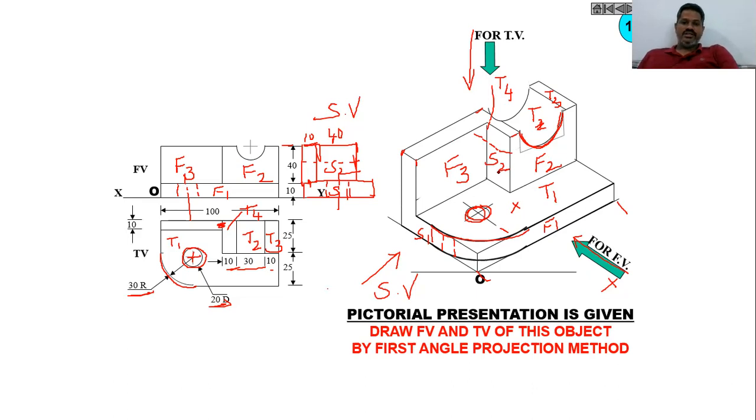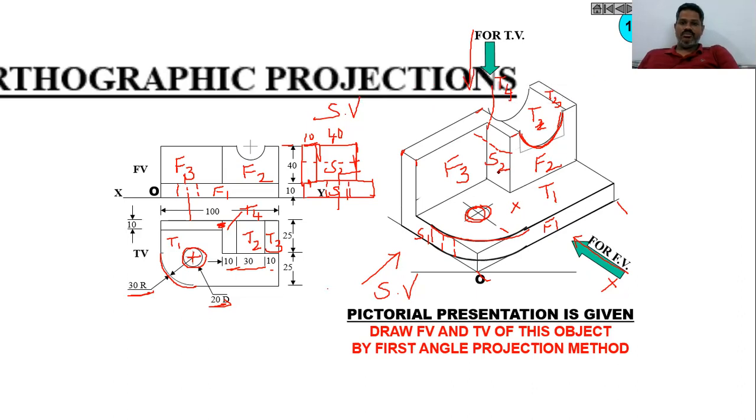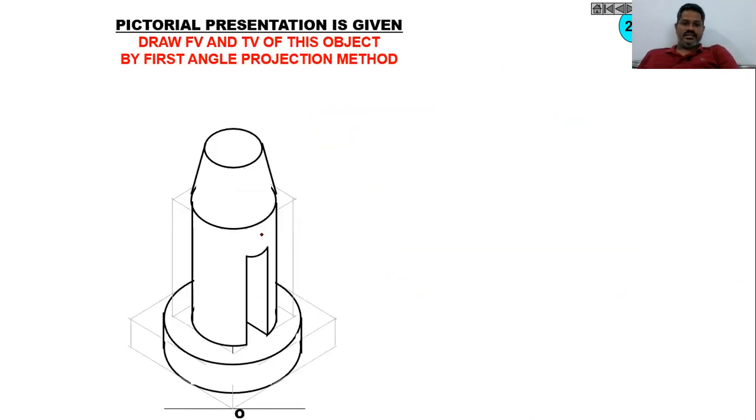Now let me move further to see another component. Take this as an example. Then this is the front view of this component. Yes, exactly. Also assume the same front view at this location. And this will become the top view for this component. Now let us draw the front view first. In the front view, we will get two circles.